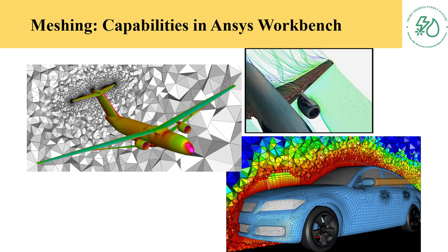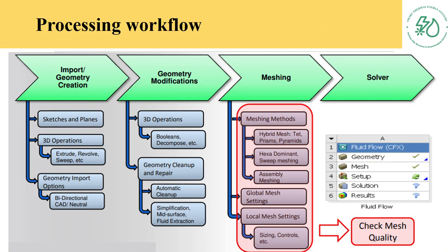The goal of meshing in ANSYS, particularly for ANSYS Fluent, is to divide the computational domain into smaller subvolumes where the equations of fluid dynamics can be solved to obtain the behavior of a fluid as it flows around an object. Meshing is a crucial step in the simulation process because it converts irregular shapes into a finite number of standard elements that the solver can work with more easily.